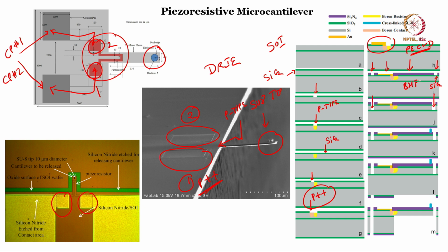When you etch silicon dioxide using BHF, you again encounter another silicon dioxide, and then what you do, you can spin coat SU8, pattern SU8. After spin coating SU8 and patterning it, on the back side you do front to back alignment and pattern the back side such that first you remove silicon nitride followed by silicon dioxide. There are silicon dioxide and silicon nitride,